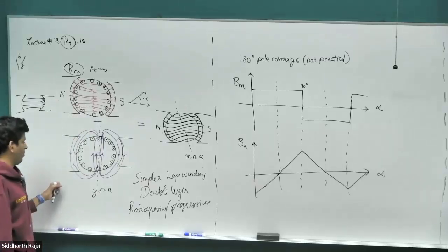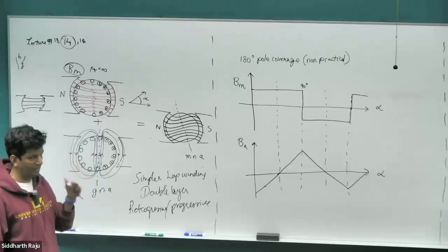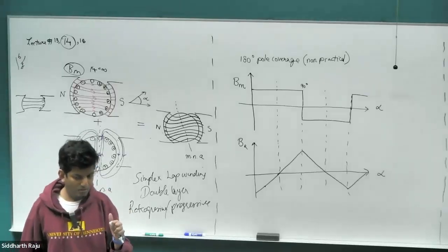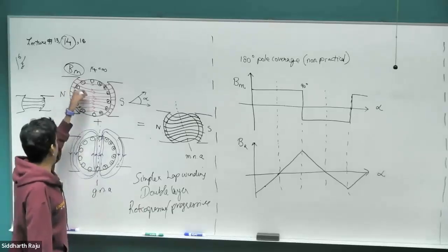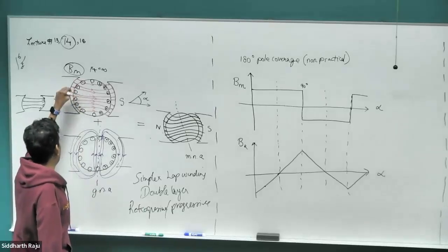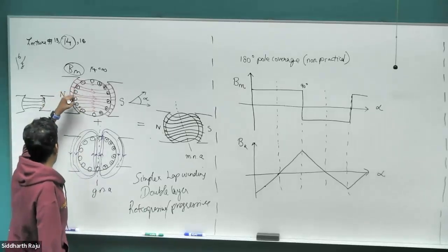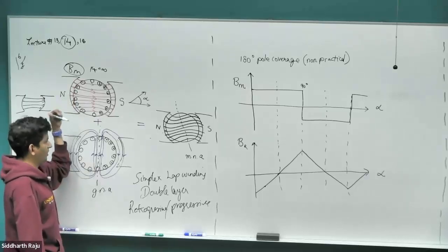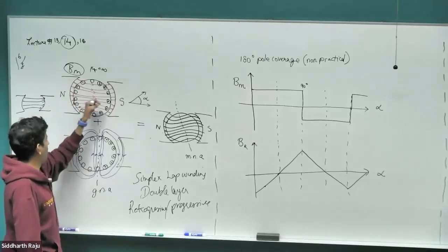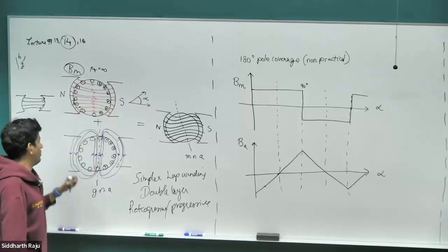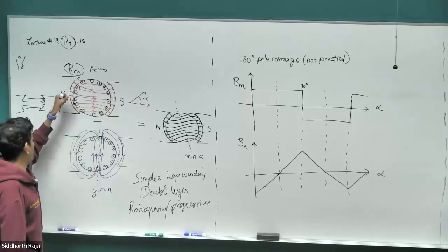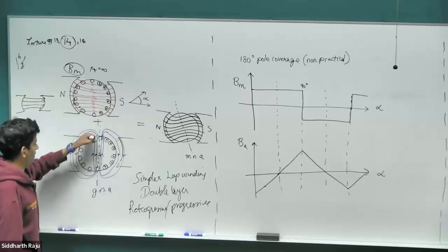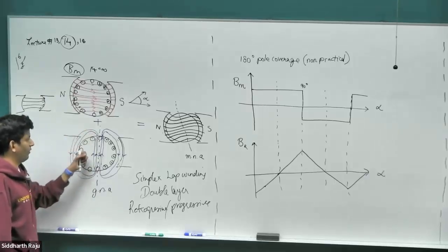So far we didn't worry about the magnetic field due to the current carrying conductor in the rotor. We just looked at the magnetic field of the magnet, looked at the current carrying conductor in that magnetic field, calculated the torque, got the expression for torque and force, and then figured out what the EMF is going to be. This is all fine in the ideal case where we completely ignore the magnetic field that's set up due to the current carrying conductor on the rotor.